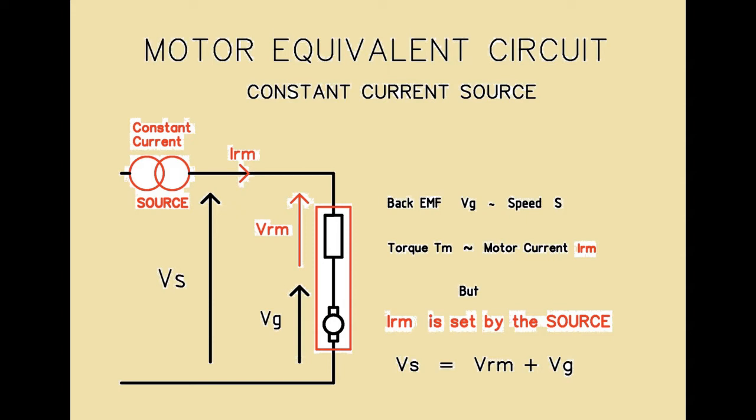Vg will increase, but unlike with voltage control, the electronics will automatically increase Vs in step with it to keep the current constant, so the acceleration will continue until the voltage supply reaches its maximum or the motor brushes start to bounce. We have a runaway situation. However, imagine that on level track we have managed to adjust the current demand to just balance friction. If we reach an incline, there will not be enough torque to balance the increased load. Unless we do something, speed will fall until the train comes to a complete stop.